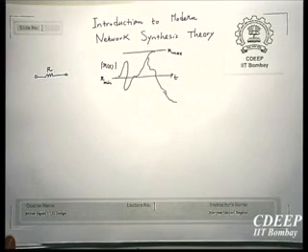X max is usually determined by the linearity of the system, and X min is determined by the noise of the system. If there was no noise, then ideally we could operate with signals as low as picovolt, picoampere, right? And any other physical quantity. And if everything was perfectly linear at any level of voltage, forgetting about breakdown and other reliability issues, I would be able to operate my system at high voltages, at least as long as breakdown and reliability issues permit.